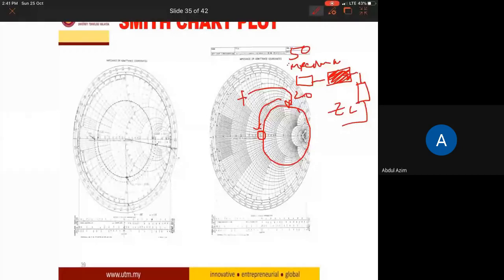So I have given the assignment, a basic assignment, using 3 ways of matching: what we call inductor and capacitor matching, circuit matching, using the stub matching, and using the quarter wave transformer. All these are 3 types of matching that you need to use the Smith chart. Besides that, you have the Z chart, Y chart, ZY chart. So this is the Smith chart.